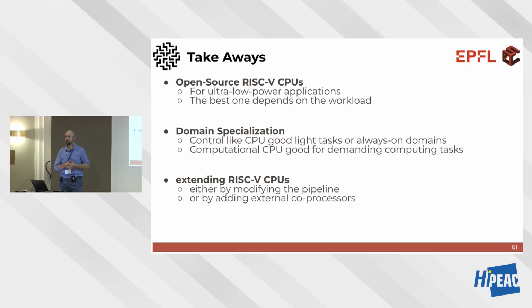And so you can play with the CPUs out there. If I forgot some, I'm sorry. But go there, play with that. That's the good of open source. There are also closed source RISC-V CPUs. Don't take home the idea that if it's RISC-V, then it's open source. Absolutely not. The ISA is open. The implementation is up to you. You can build your own CPU, make a company, and sell it. There are companies doing that, by the way.